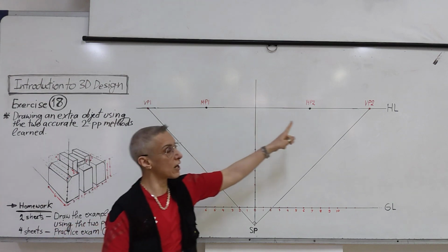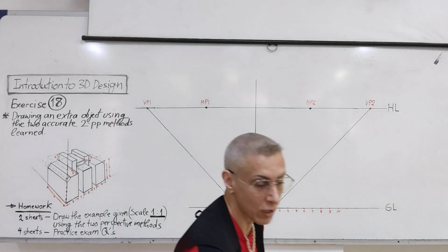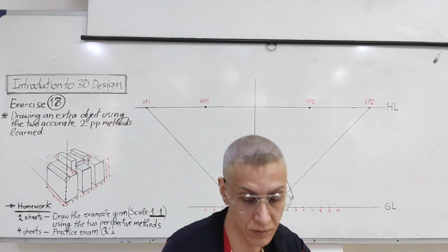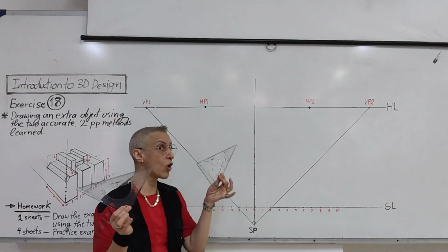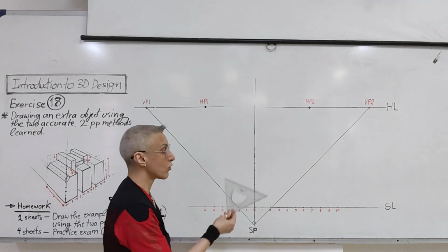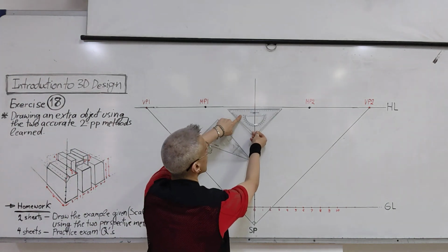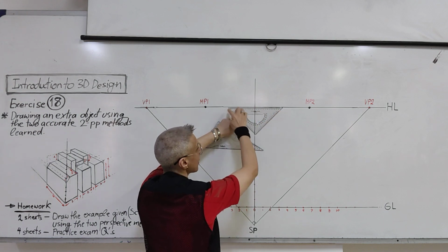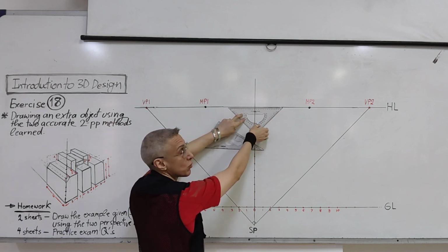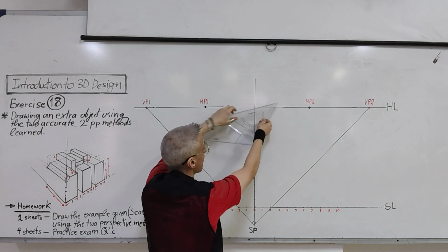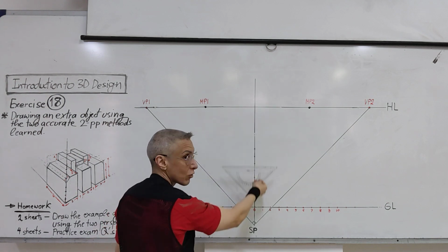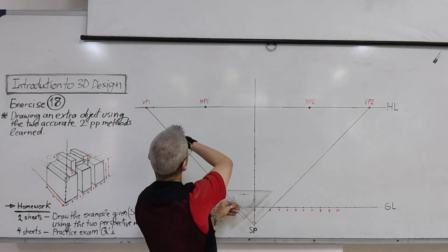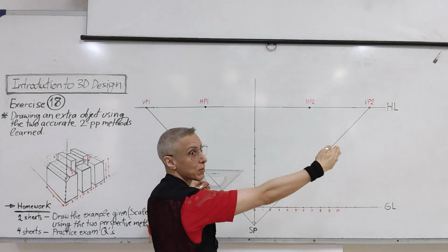So you start with the horizon line. Then you need to select the two vanishing points. And you can do that with either this ruler or this ruler for this method. So if you choose this ruler, you have to place it exactly on the line. And of course, here and here could be the vanishing point, but they will be too close to each other. So this is a bad idea. You have to move it down so to have sufficient space. And then extend the lines. Then in this case, the vanishing points will be more far away.